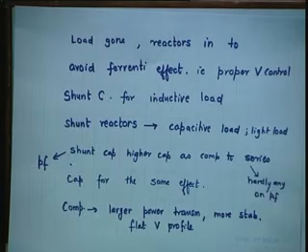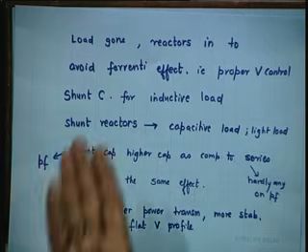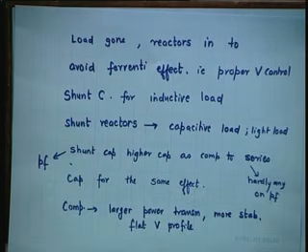So, shunt reactors also play a very important role in compensation. Do not think that they are not required. Light load, yes, no load or light load. Of course, shunt compensation is required for inductive load, and most of the load is inductive in real life. All right. If you have a capacitive load, obviously you use reactors.